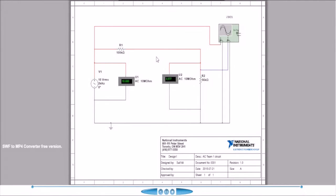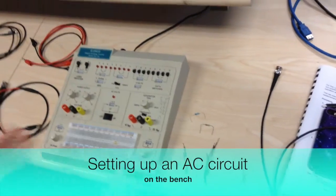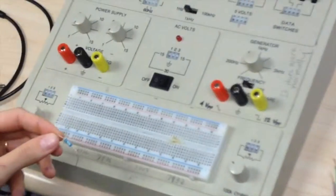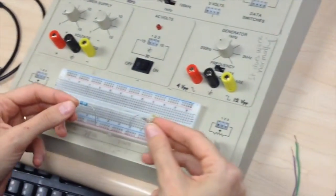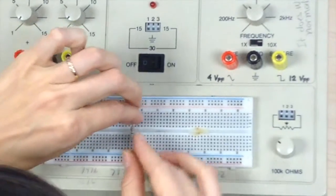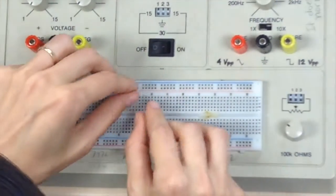Now we're going to set up our AC circuit on the bench. Here is R1, which is 100 kiloohms, and this is R2, which is 56 kiloohms. We're going to connect R1 to our power strip, and also along the same row here is R2, which we're going to connect to our ground.